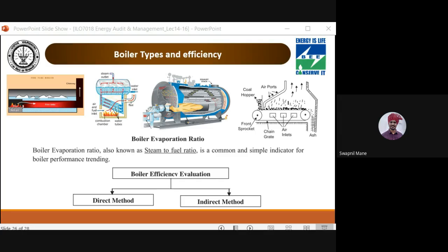So even if the boiler firing temperature is 1300 degrees Celsius, when the burnt coal reaches the chimney, a considerable drop in temperature will take place, to around 120 degrees Celsius, and SOx will try to condense on the inner portion of the chimney, forming a scale of SOx and NOx in the inner part of the chimney.